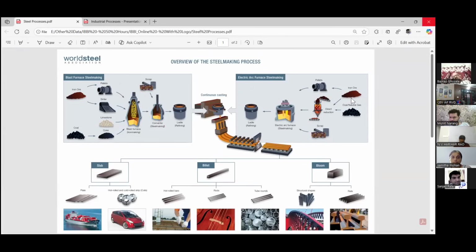Same type of another process. Your iron ore and coal in specific ratios are fed to the kiln. In the kiln, from one end we are firing. So a mixture of iron and coal plus firing of the coal. The process done there is the DRI process, direct reduction of iron.